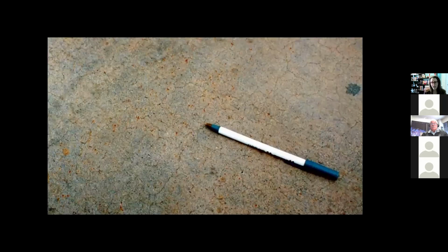There are other forms of scaling that can occur that are durability issues. You may not even see it well in this photo, although it is an excellent photo of it. At the tip of the pen, you might see some fine hairline cracks. The reason these cracks occurred in this picture, which comes from the Federal Highway, is due to the sand being chemically reactive with high alkalis. So this is ASR, alkali silica reactivity in the sand.